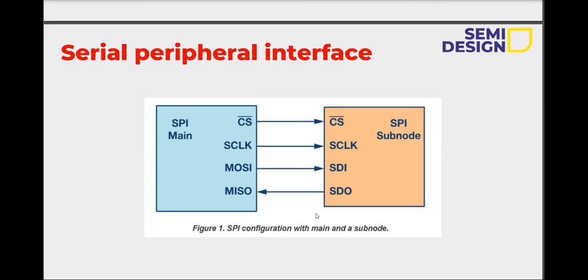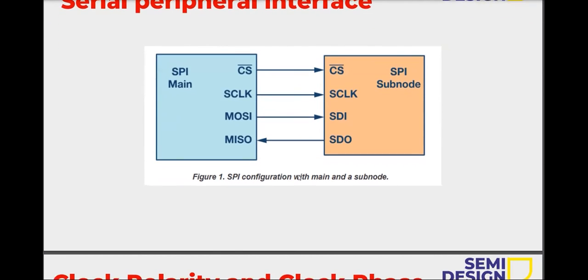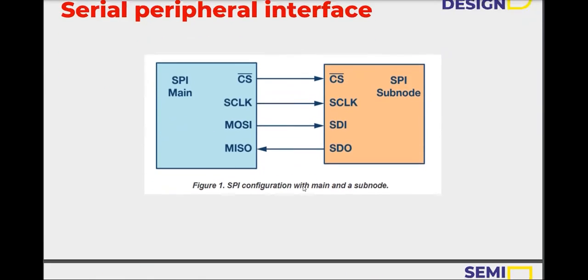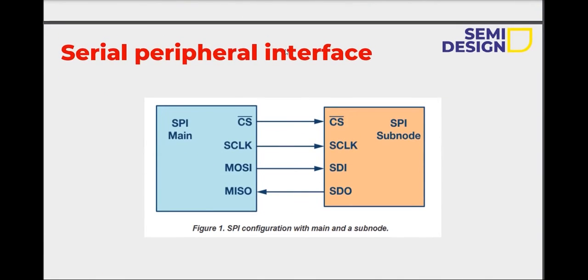So during the SPI communication, the data will be transmitted simultaneously. It is shifted out serially onto the MOSI, or serial data out, bus. It also receives simultaneously the data on the bus, whatever MISO is there, it will sample and read it simultaneously. So this SDI and SDO are nothing but the MOSI and MISO of the slave.